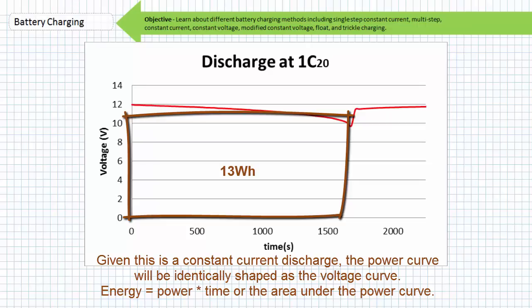When tabulated, let's say each battery yielded roughly 13 watt-hours of energy. Notice that when the discharge period ends, the battery open circuit voltage bounces back to roughly 12 volts when the chemical reactions stabilize. This roughly corresponds to a battery with only 20% state of charge remaining. Additionally, note that with such a high discharge rate, this battery yielded only approximately 47% of its nominal 12 volts times 2.3 amp hours, or 27.6 watt-hour capacity before reaching the predetermined cutoff voltage. Those with an understanding of the battery discharge characteristics lecture will appreciate that when discharged at such high rate, this battery is behaving as expected.